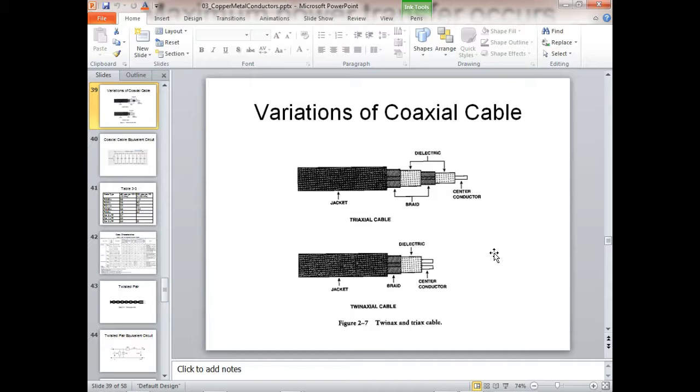But if we went over there to the big FANUC robot and you see all those directional control valves and everything, we don't run a wire to all of them. We run a communication cable to them called devices. Every one of those devices has a little address switch on it. So you address it like device 126 or device 128. And then your robot controller, if you wanted to energize that thing, would just send out that address on the cable, and then everybody else would just do what? Ignore it. So that's one of the ways we do that.